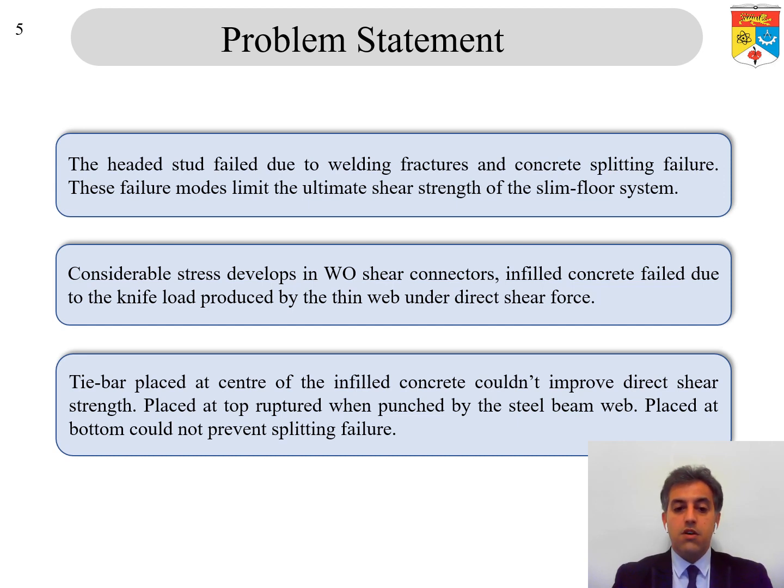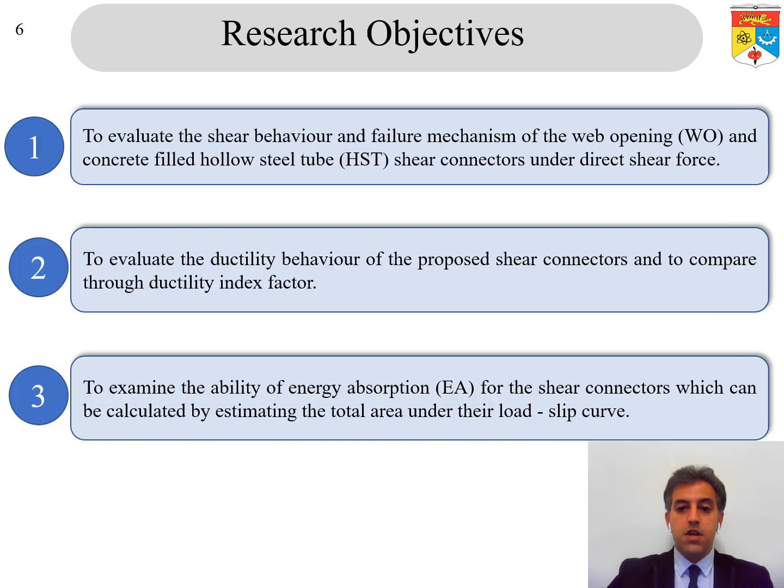The tie bar placed at the center of the infilled web opening shear connector couldn't improve the shear strength of that type of connector. The same goes for the tie bar placed at the top, which ruptured when punched by the steel beam web, and the tie bar placed at the bottom could not prevent the splitting failure of those types of connectors.